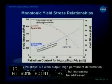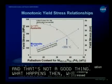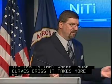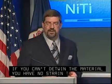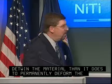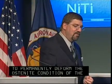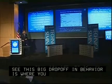What that implies is that where those curves cross, it takes more stress to detwin the material. And if you can't detwin the material, you have no strain to recover back. So it takes more stress to detwin the material than it does to permanently deform the austenite condition of the material. So right around 350 degrees C, where you see this big drop-off in behavior, is where you get this crossing of the two plots.